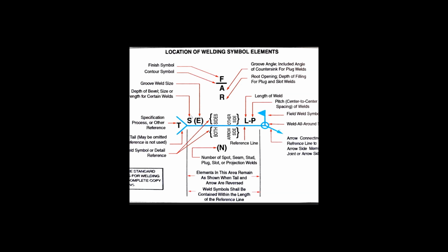Whenever you're looking at blueprints, you're typically going to see one or two different styles of numbers here. You're going to see a fraction or a decimal. The fraction, of course, leads us back to imperial. The decimal can either be metric or imperial. So if you see something like 1.25 and you don't see any kind of indicator after it, like millimeter or centimeter, always assume that it's imperial, meaning 1.25 inches. If it's going to be in the metric system, you're always going to see the abbreviation for millimeters or centimeters coming right after the number.